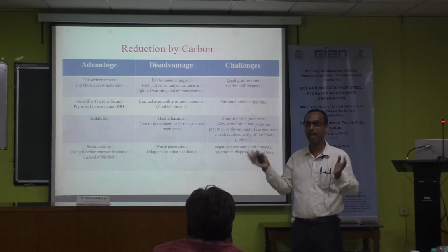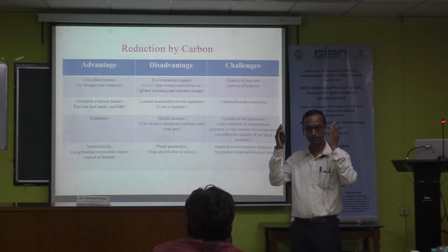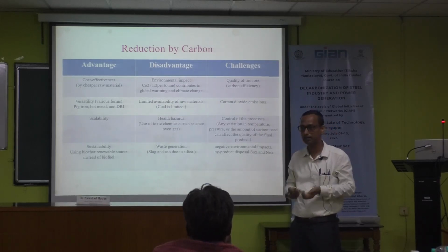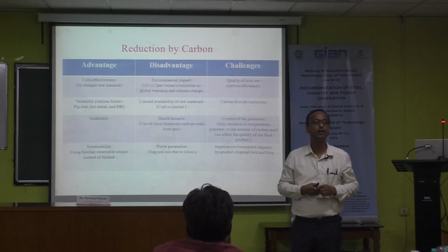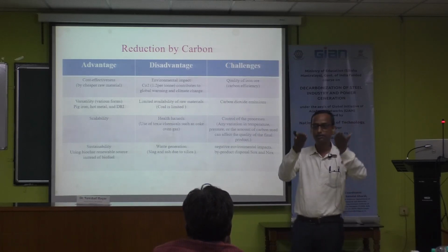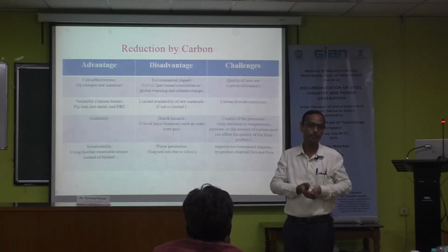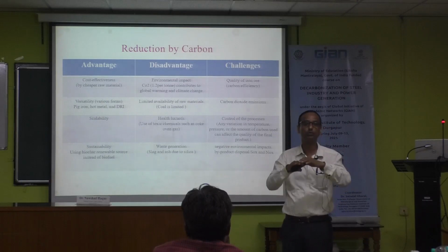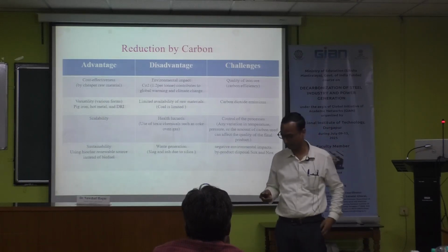This slag also is required to be heated to a liquid temperature so that you can separate it. Because of the separation mechanism in pyrometallurgy, you have to enhance the temperature so that the metal and slag, meaning impurities and the metal, are both in a liquid phase.